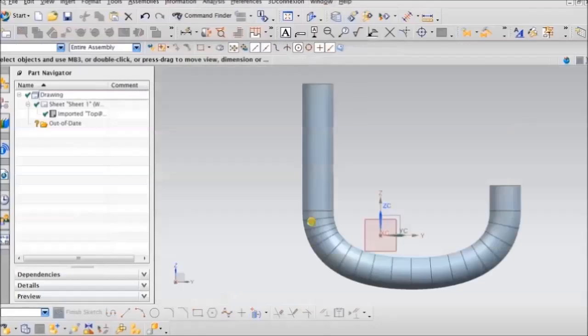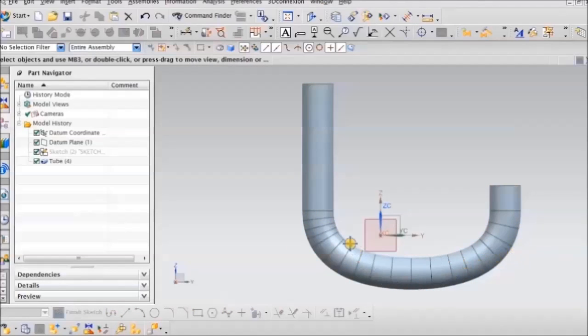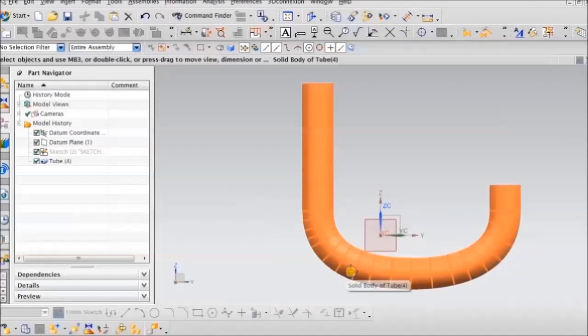This happens because we have multiple surfaces over here and the dimensions were attached to one of the surfaces. So in case you have a parametric model, you have to make sure that your dimensions are updatable. You can either avoid the dimensions which are attached to features like this, or you can use other techniques which are described in tip number 3.